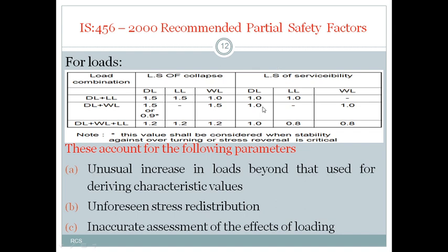That is, in limit state of serviceability, for dead load it is 1, for wind load it is 0.8, and for live load it is 0.8. So the reason for providing the partial safety factor in load is because of these reasons. That is, unusual increasing load may take place during its service, unforeseen stress distribution may take place, and we may inaccurately assess the effect of loading while designing the structure. To overcome all these problems, these partial safety factors are used so that we can design a serviceable and safe structure.